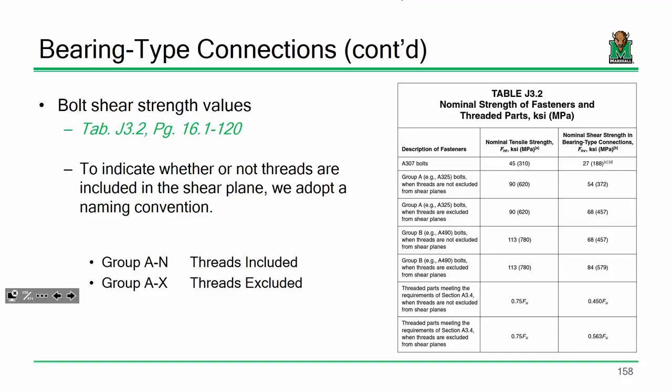One way to design a connection is to design for the loads. We're not designing for the plate. We're saying, okay, we have a dead load of 50 kips and a live load of 80 kips. Pick the number of bolts for those loads. That's one philosophy of connection design. The other is to design the connection so that it doesn't fail, that the plate fails. That's a whole other can of worms.